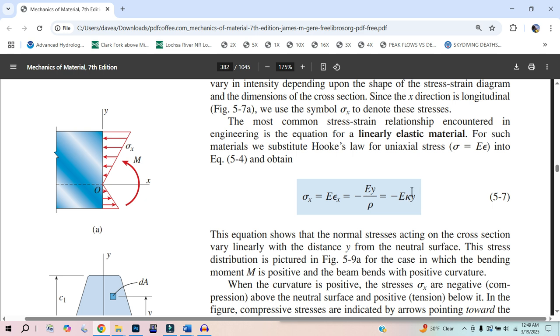This y can be in a negative y direction or a positive y direction. And this negative was just from our equation. So you've got three things that could be negative. You could have negative, negative, negative, and that would be a negative curvature due to two negative moments, and then a negative y direction. So you'd have a negative, negative, and a negative. So that would be a negative strain. And is that what we would find?